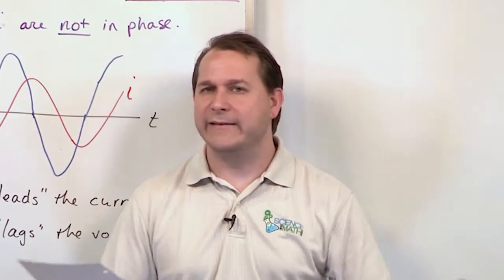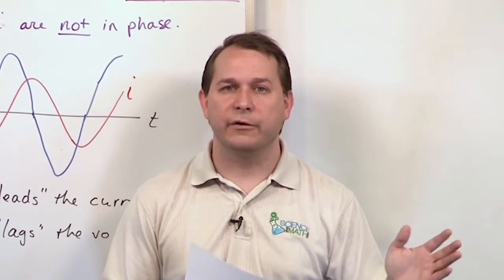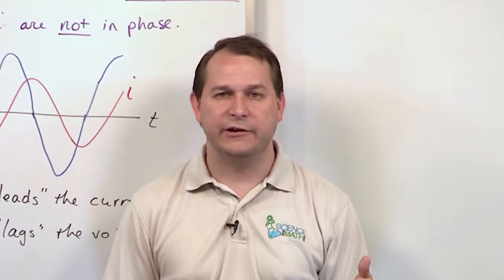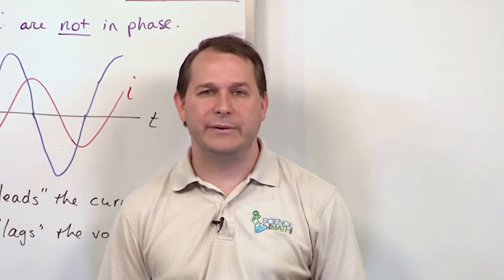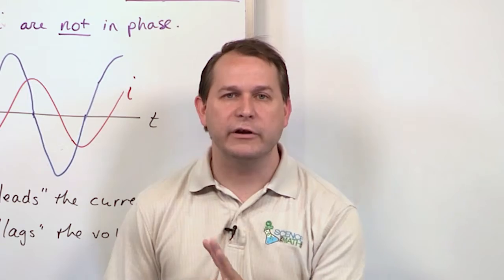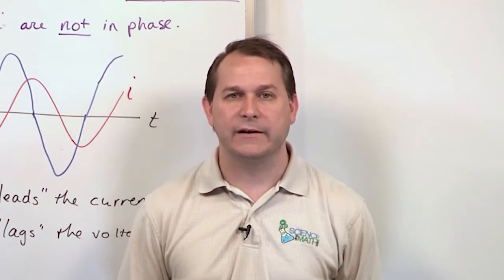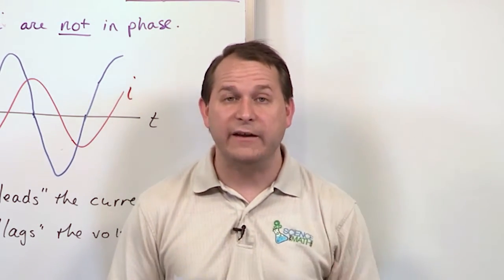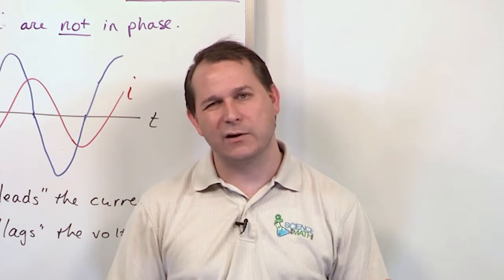The resistors will stay the same. The inductors, you'll convert to the impedance we talked about in the last section. The capacitors, we're going to talk about its impedance here. Once you know how to convert all the circuit components, and we've already talked about how to convert the sources to phasors, then you can actually do some analysis. So we're kind of walking through here.